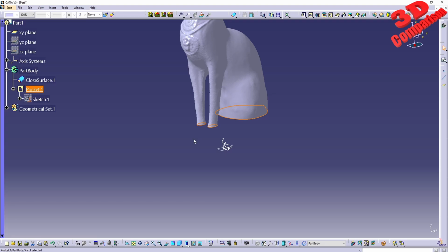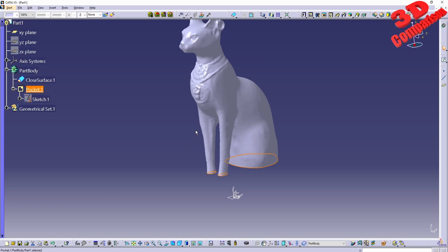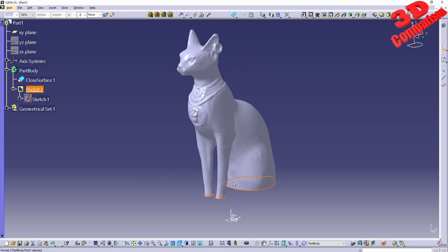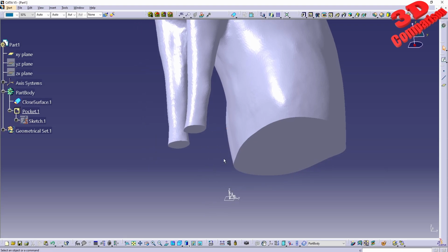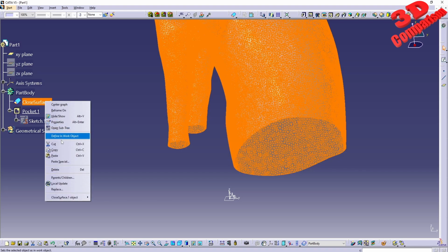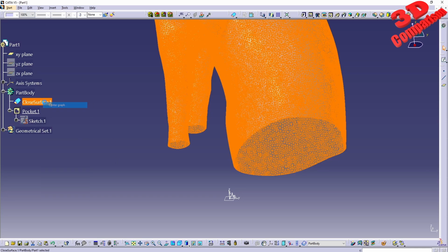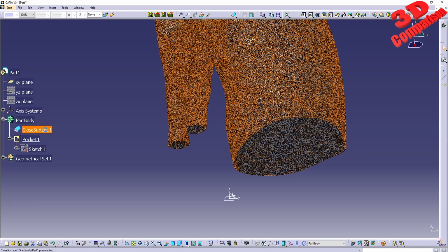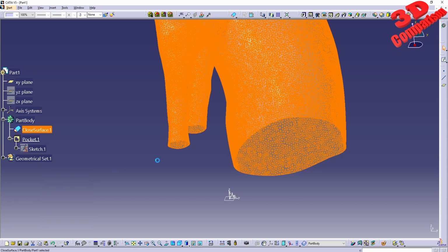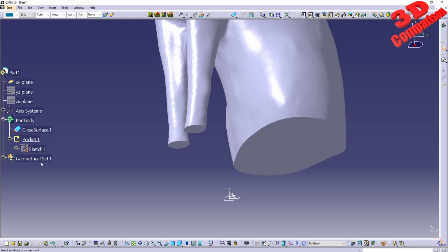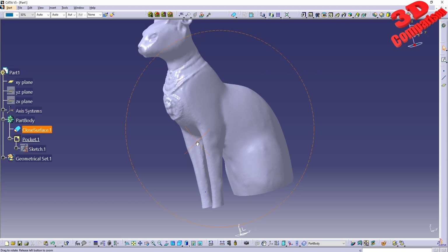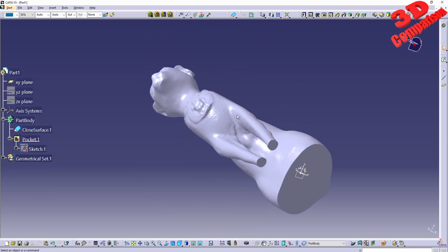Okay, and we have the extrude process over here. Now, in the video I've trimmed this and it didn't take a lot to process, but in this case I recommend taking this closed surface and copying it and pasting special as a result within a new part and working over there with that, because then it will not take so much time to process. Over here this closed surface is linked to the join and the other surface, and that will heavily increase the processing time.